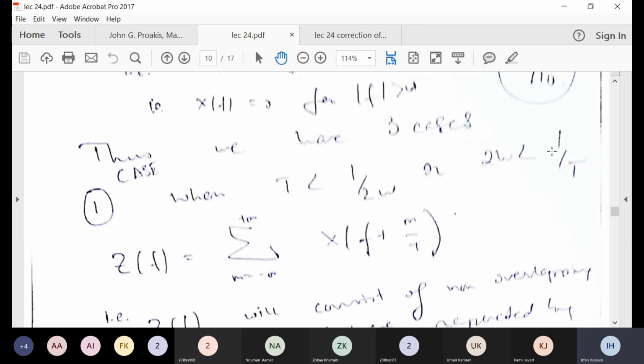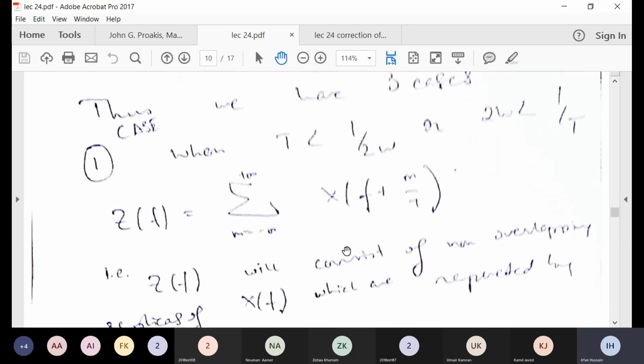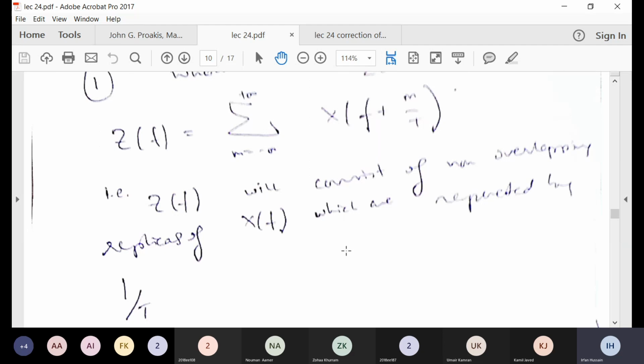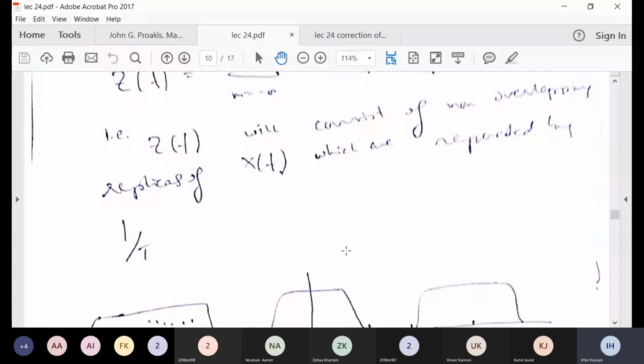So if your periodicity or your repetition is greater than the bandwidth of one W and the bandwidth of the other replica W, so if 1 over T is greater than 2W, then this means that you will have gaps in the spectrum where you have replicated X(f). You are replicating, but there will be gaps, and hence you won't be able to satisfy the condition of constant value of Z(f), which was required to be equal to T,